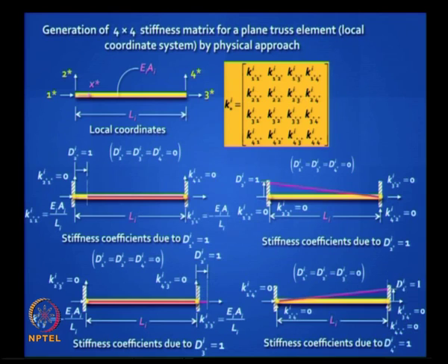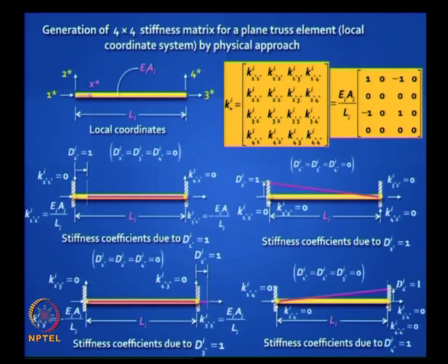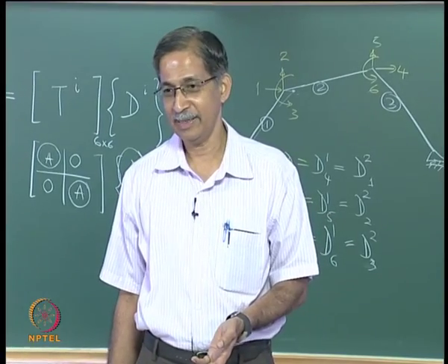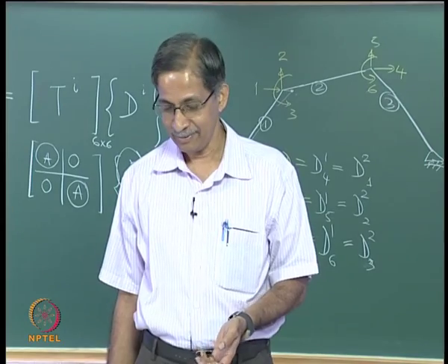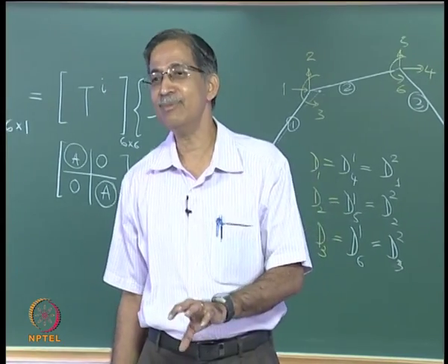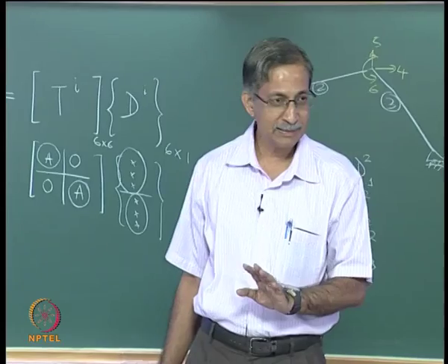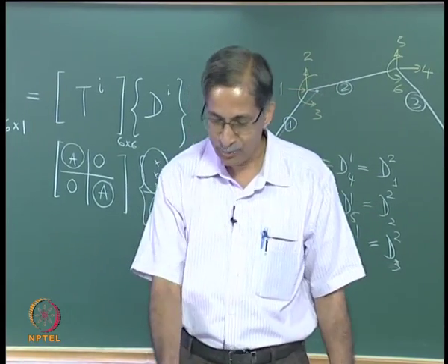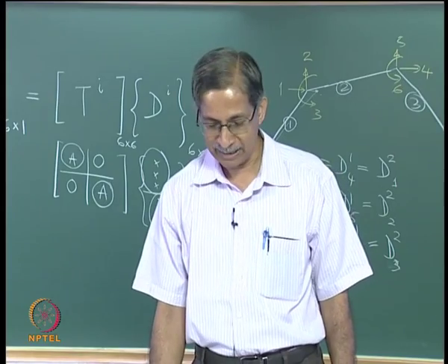So what does that matrix actually look like? Fill it up. It's got a lot of zeros in it. So sometimes your stiffness matrix looks like this, which is why the reduced element stiffness method said, why should I put a lot of zeros? I don't need those zeros. So it becomes smaller. Have you got the hang of this? Is this clear? But then the question is, why should we have such a matrix? How is it helping us?